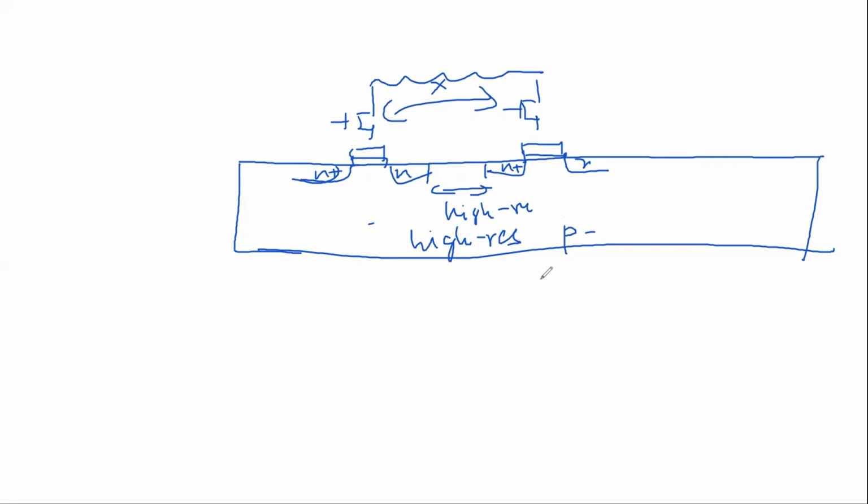So in that case, I actually want this to be a p-type material, not an n-type material. Depending on the circuit, we might need a high resistive material or a low resistive material. But what Puneet was saying, for example, in a CMOS, like that first gate I showed you, we want a switch from VDD to the output load, charging this. This one, it is efficient to have a P-type. This is efficient to have an N-type.